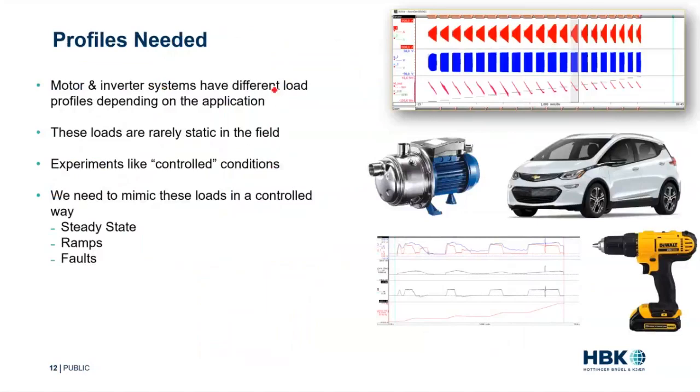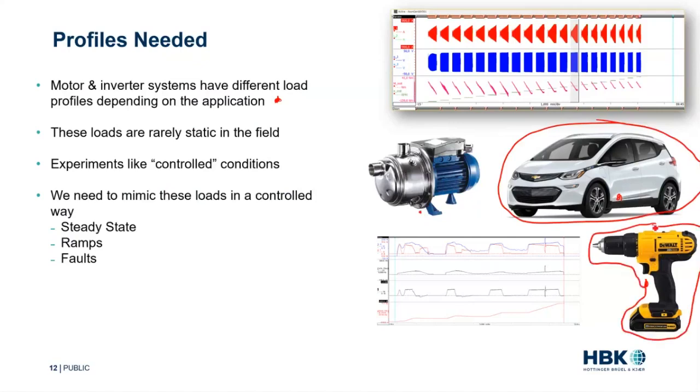And motor and inverter systems have different load profiles depending on the application. I don't think many people here are going to be testing pumps as well as cars, as well as drills. But if you're the guy testing the car, you need to know, all right, am I just running static points? Am I running ramps? Am I running WLTP drive cycles? If you're the drill guy, you need to know, am I running steady state? Am I running pulse conditions? Am I running operator conditions? What's my drive cycle?